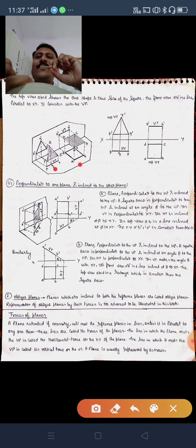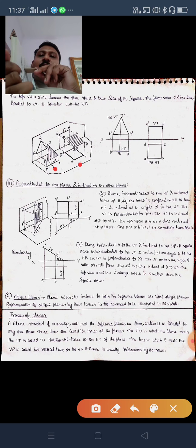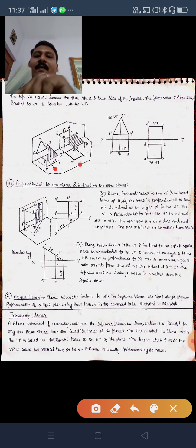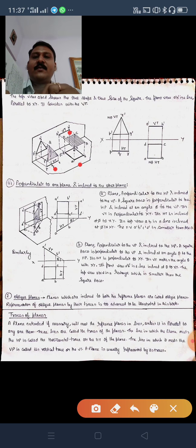So if you see this square from the front view, this is front. From here if you are seeing, so definitely this will impinge on this plane. And if you see from the front, you will see only a line, this plane. You will see only this line. Okay, so this will impact over here, and this will be your front view, as it is clearly mentioned in the diagram. You can see here. Similarly, if you see the top view, then from top you will see this upside plane, and it will form the image in this horizontal plane, like this. So it is also mentioned over there.